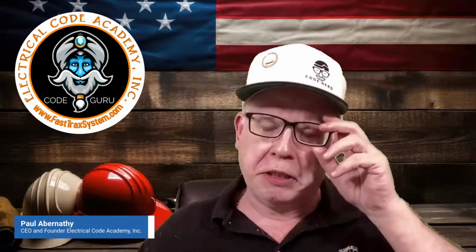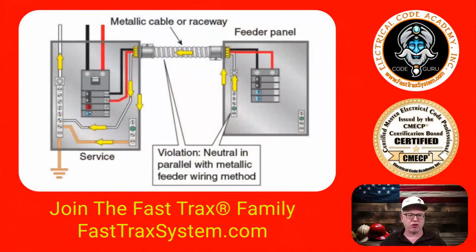All right, so here's the illustration that we were talking about. So here you have your service conductors coming in. All right, and here's your main service disconnect. Here's your grounded neutral conductor coming from the utility. Okay, it's coming in, and you see this bus. Now, just to let you know, see this conductor right here? This is a main bonding jumper.